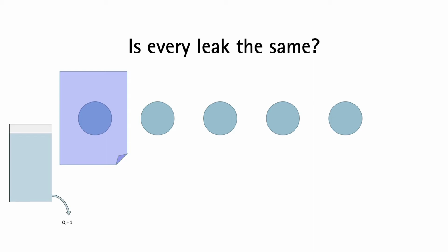The thing that's driving the airflow through the leak is pressure. It's like pressure in a glass of water with a leak at the bottom. As long as the height of the water stays the same, the pressure behind that leak stays the same, then it doesn't matter how many holes you poke into the can, they're all going to leak the same.